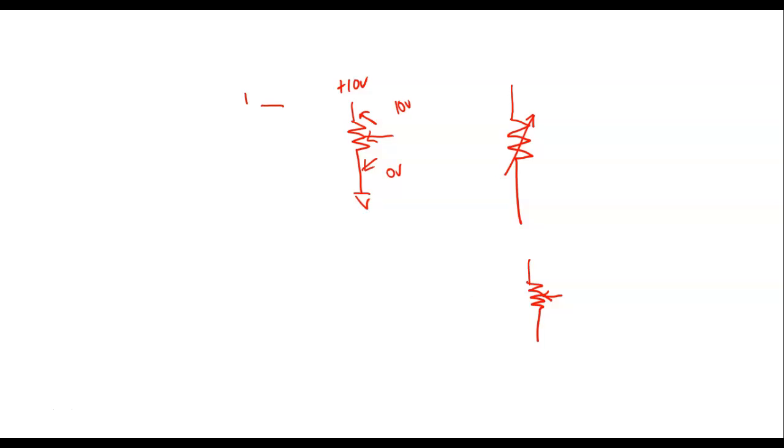So what we can do with this is a variable voltage divider, which means we put a voltage on top, and then I can divide that down in any ratio between the maximum voltage all the way down to 0. So that means our circuit is going to look like this. I'm drawing this backwards, guys. And so here's my common. I'm not going to draw the negative supply.